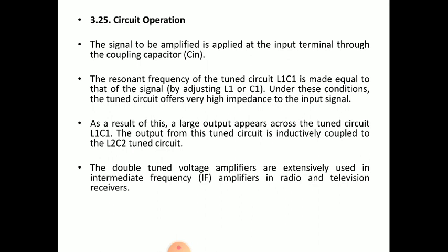The tuning circuit, single tuned amplifier circuit concept. L1 C1 are selected such that F0 equals 1 by 2 pi root L1 C1, which is equal to the input signal frequency which has to be amplified, and as a result of this, a large output appears across the tuned circuit L1 C1.